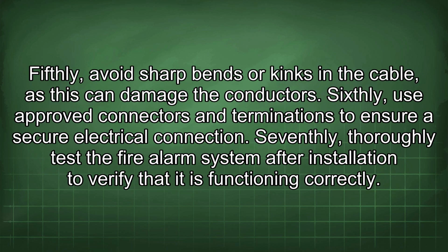Fifthly, avoid sharp bends or kinks in the cable, as this can damage the conductors. Sixthly, use approved connectors and terminations to ensure a secure electrical connection. Seventhly, thoroughly test the fire alarm system after installation to verify that it is functioning correctly.